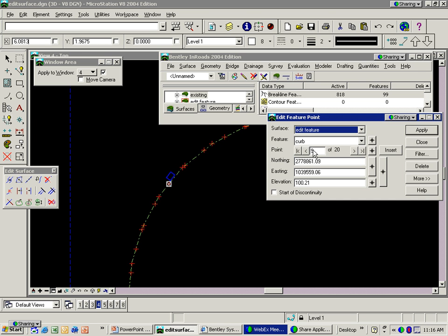So we're on point number 9 out of the 20 points to find this curb return. If we look at it, it's elevation 1021. We could progress forward. We have 1040, 1046, and 1030. This area in here with this inlet being stuck in this location is not going to have positive drainage. So what we could do simply is use these tools to modify what's going on here.